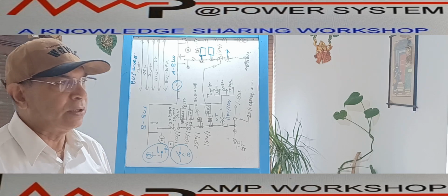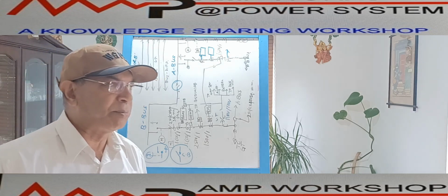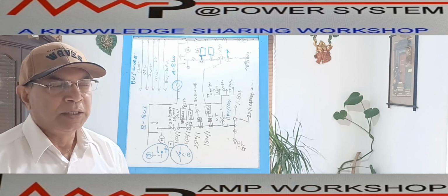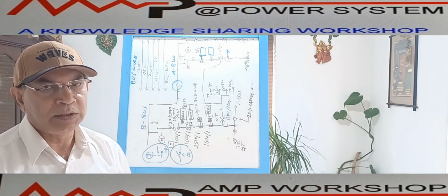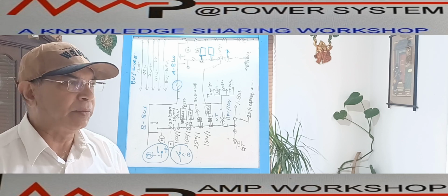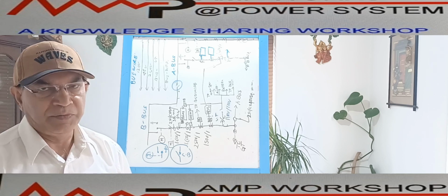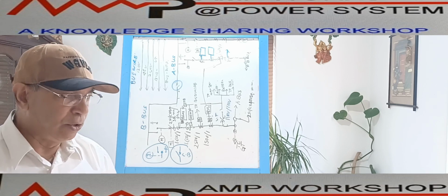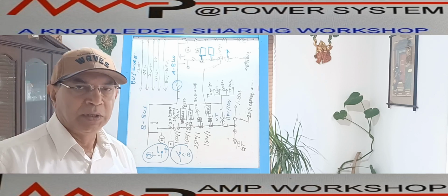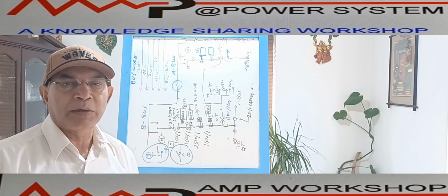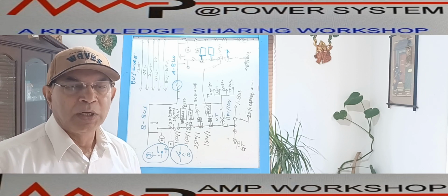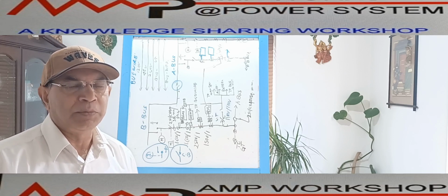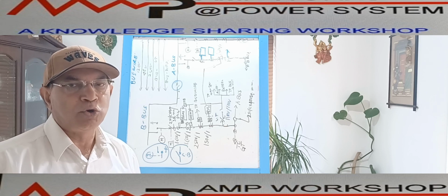Based on that, we have conceptually decided that for this 11 kV switchgear, the generator feeders, or otherwise very emergency or urgent equipment like generators, or, suppose, gas compressor motors, those types of equipment will be supplied by dual feeder.